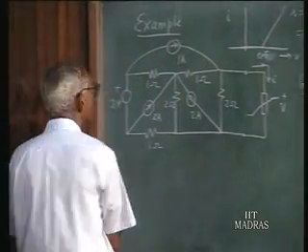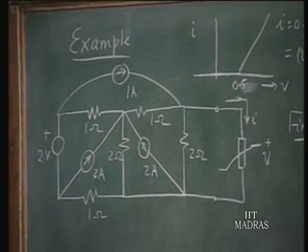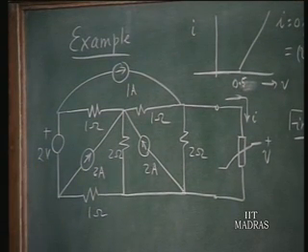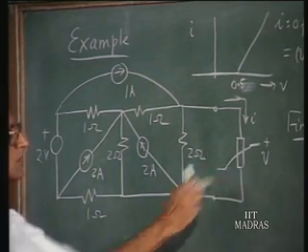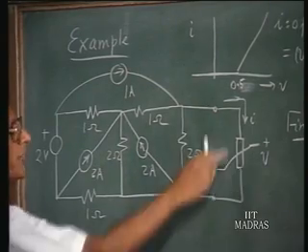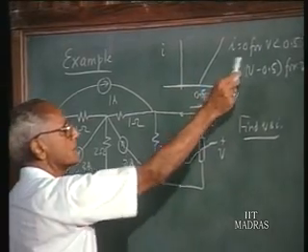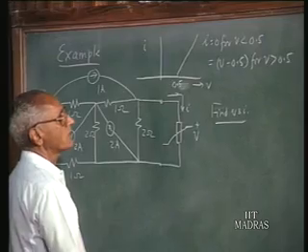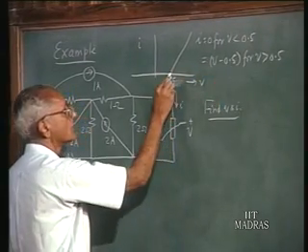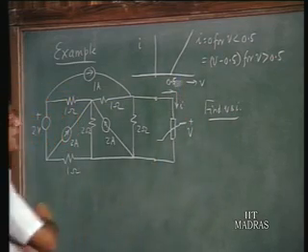We have here a network with various resistors and independent DC sources, along with an element here which is nonlinear. This particular element has the VI relation sketched here and described by this equation. The current is 0 for V less than 0.5, and once voltage exceeds 0.5, current linearly increases according to the formula V minus 0.5.